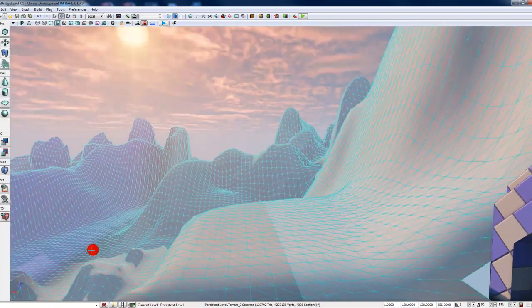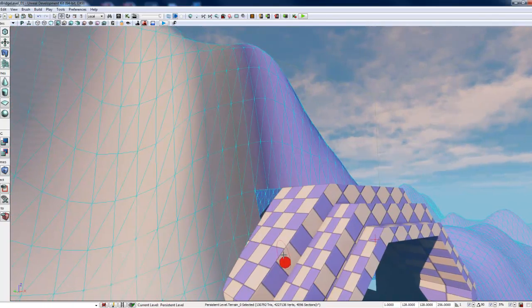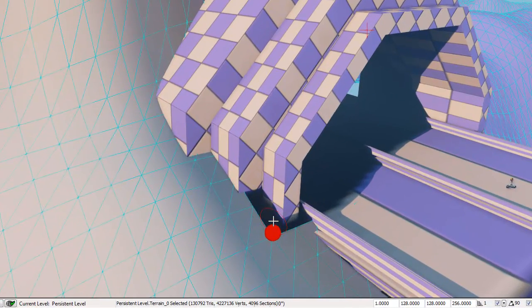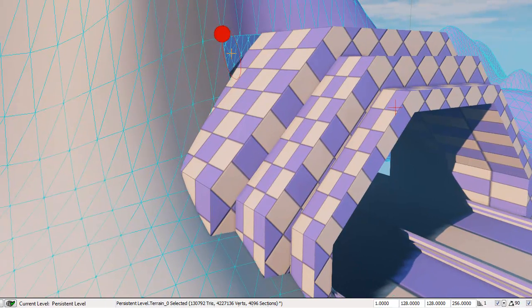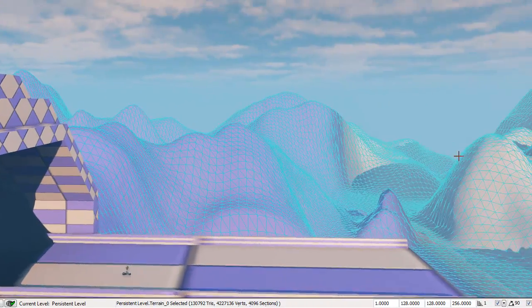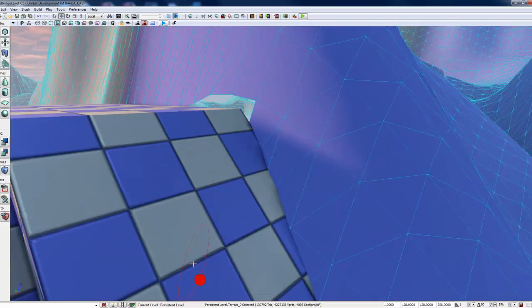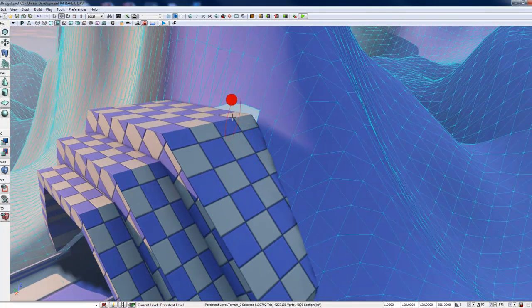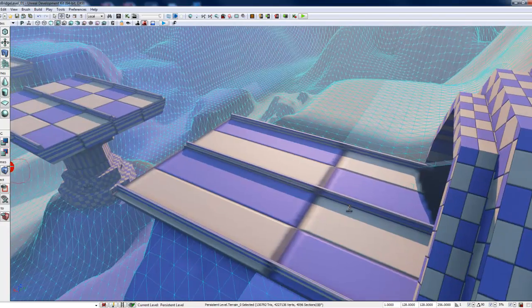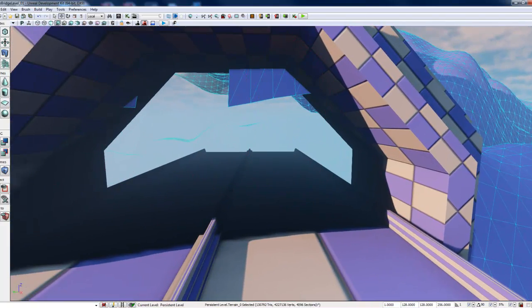Okay, so I've cut too much off here, and I've cut a lot off at the top. To get that back, just press Control and right click. So to cut is left click, to paste back in is the right click. There we go, this back in. Gotta find out where it wants it. Change the radius a little bit. There we go. And change that radius again.